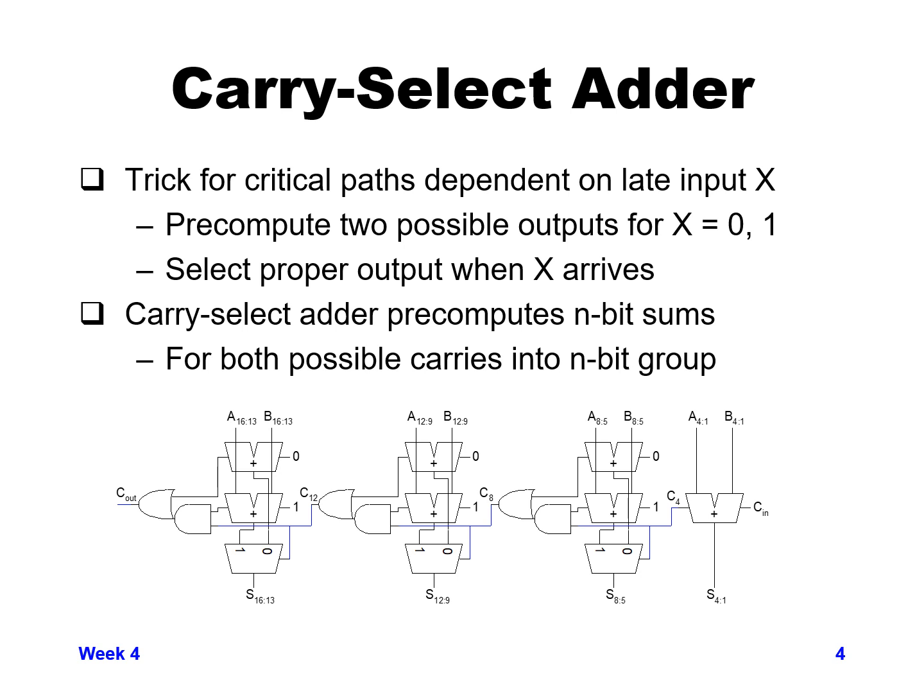So another trick that's sometimes used is what is called a carry select adder. And this is a trick that you can use for not just adders, but for other functions as well, where you know that you have maybe 2 inputs that are fairly stable and there early, and you have 1 input that might come in later.